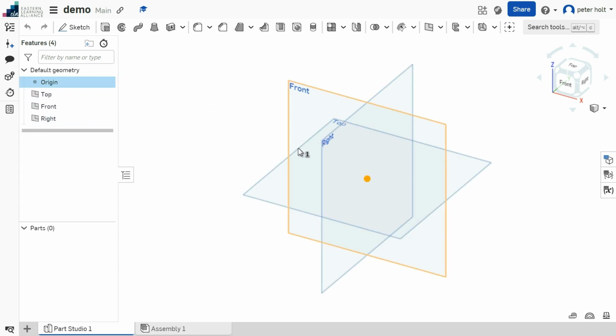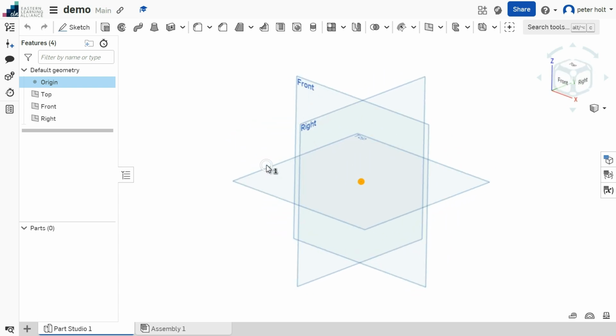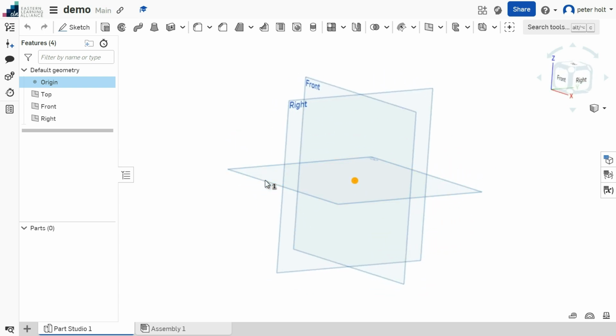We can zoom in and out with the roller ball on your mouse, but you can also right click and left click to tilt and rotate. Wherever the mouse is, that is where it's going to zoom in on. So if your mouse is all over here and you zoom out, then it will zoom out away from that point. And when you zoom in, it will zoom into it. So you can lose the origin.